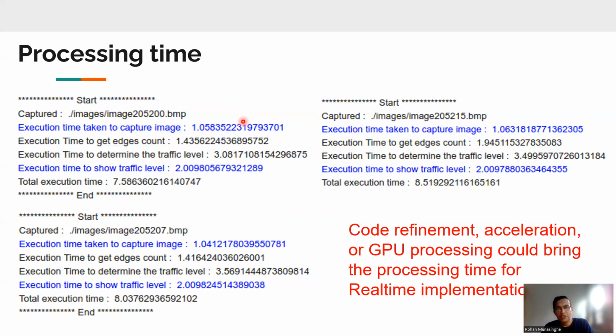So if our decision can come within that minimum time, let's say 4 or 5 seconds, we can call it real time. So you can implement even this algorithm in real time. All you need is a Raspberry Pi camera and the software. That's it. And you need to get the Raspberry Pi to communicate with the PLC, which controls the traffic light, right? Then it is adaptive traffic control. So that's how you build a simple yet very effective adaptive traffic control.